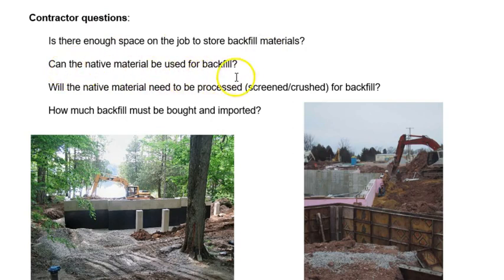Can native material be used as backfill? So the material that was taken out, can it be put back in? Or does it need to be processed or mixed with other material? So screened, meaning taking things that we don't want in it out, or does it need to be crushed? And does backfill need to be brought in and imported?